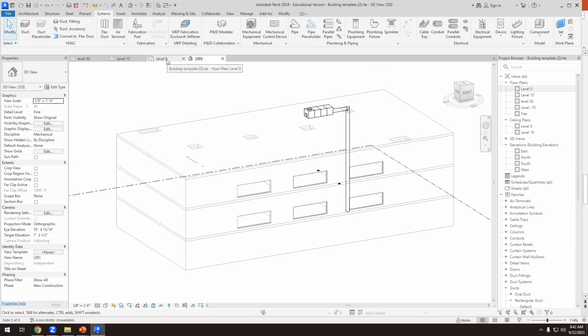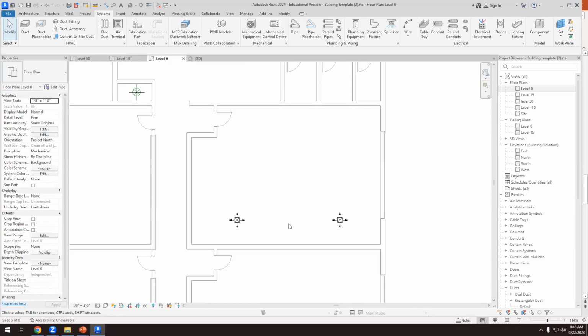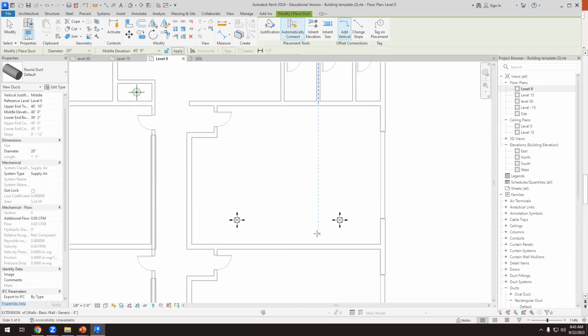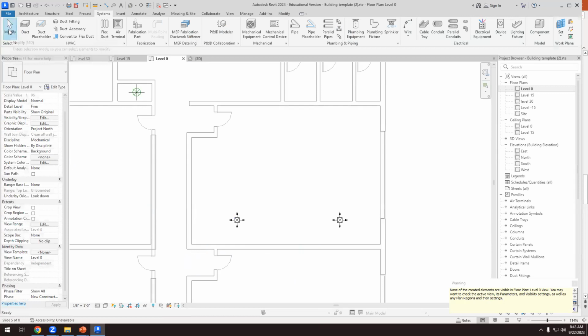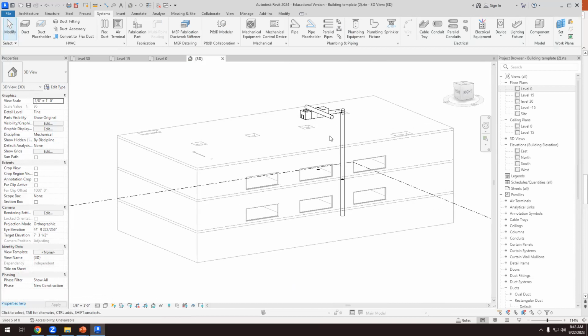So now, what's next? We have to work with ducts. We can create a duct. By default, I think we use the 20-inch diameter. Let's do this, and then we will change it. So we can stay here. And what is happening? Why don't we see the duct? Because Revit has decided on my computer that the duct is up there.